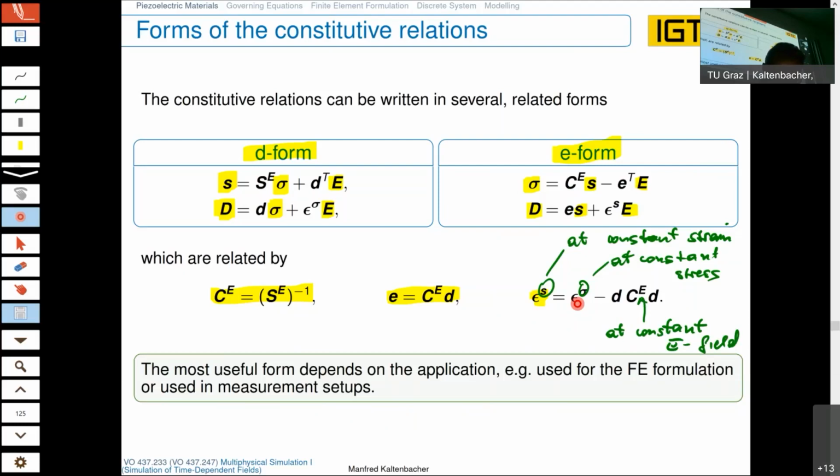And in addition, we also have to be careful. We also have to evaluate, as you can see here, for example, our classical Hooke's law, where we try to get the entries of the mechanical stiffness tensor at constant electric field. How can we have a constant electric field? Because we have this full coupling, so any change in a strain will also give a change in the electric field.